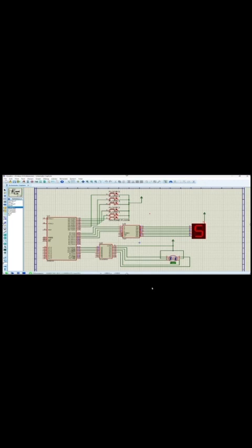The driver IC is a transistor array used to amplify the current for driving higher load components like motors. It is connected between the microcontroller and the motor. The decoder displays the current floor number. The motor represents the elevator motor, whose direction and control are handled by the microcontroller through the driver. It simulates the elevator moving up and down between the floors.